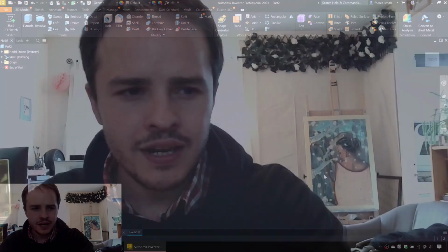Beautiful. Okay, so it might be worth talking about when you do have a complicated shape, how do you begin to describe it? I find that it's very useful to see where it interfaces with other things, the functional components. So in the case of this guy, what we've got is a shaft here and a shaft here. Now, pertinent to the overall geometry is probably the relative angles and positions of these 2 shafts. So we might start off by creating a cylinder to represent this shaft here, and then another cylinder, or a barrel shape as it appears here, to represent this one. And then we'll come in with the connecting geometry.